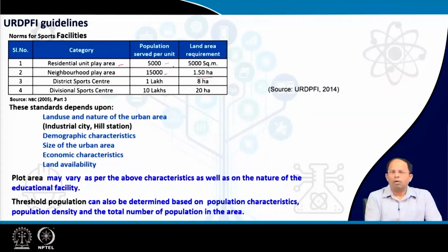So definitely, as you can see, these values are given, but if a neighborhood is of a small size, or maybe a city is a very low density city, right? There are smaller neighborhoods. Shouldn't we have a residential play area or a neighborhood play area? If it doesn't match the size of 15,000 people, we still should have it. Then should we proportionately reduce the size of this particular facility?